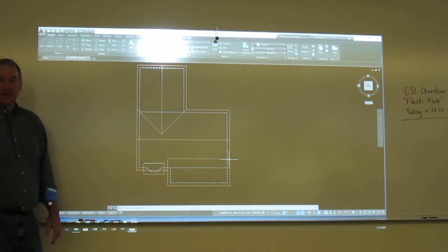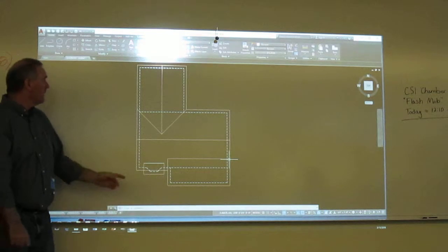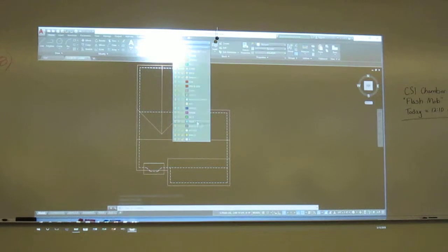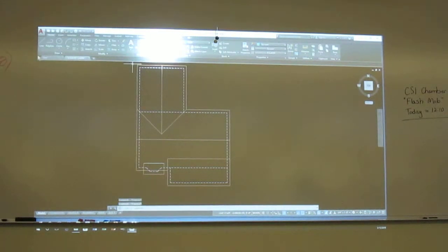Next thing we're going to do is add our framing node. So let's make that triangle right off the bat. I put these on the text layer because in essence it's a text component. So let's go to that layer, make it current, do the polygon command, three-sided equilateral polygon. So 3 sides.